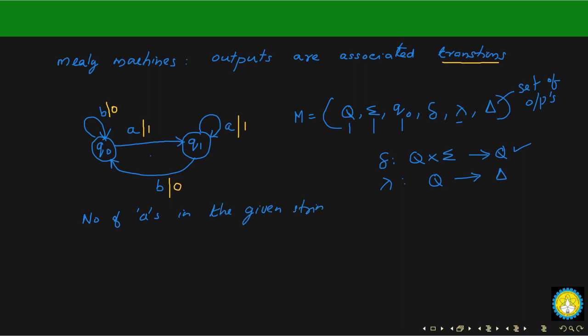So we will also design some more Mealy machines. In fact, we can design Mealy machines for all the problems for which we have designed Moore machines, and we'll look at some more problems for designing Mealy machines. Again, one very important thing to remember here is that in Moore machines you had a default output. If you look at the starting state, in a Moore machine there was an output associated with the starting state, but in a Mealy machine you will get an output only upon transitions.